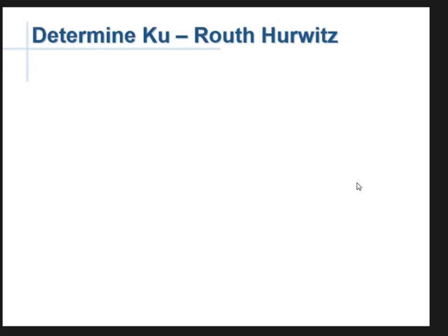And that's indicated in our Routh-Hurwitz by sign changes in this first column. So if this term or this term becomes negative, I've got an unstable system. If I find out where these two are equal to 0, I've got my marginally stable condition. I'm just on the boundary between stable and unstable when those terms become equal to 0.